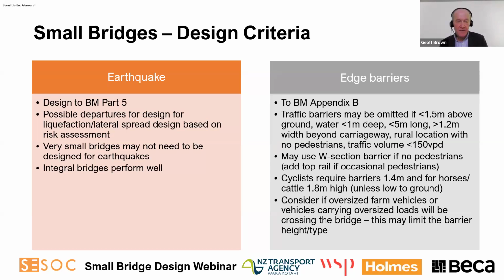You also need to consider if oversized farm vehicles or vehicles carrying oversized loads will be crossing the bridge, because this may limit the barrier height and type. Next slide, please, Jamil.